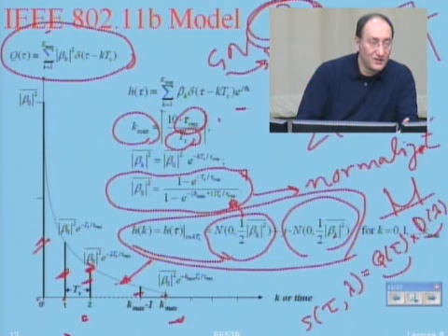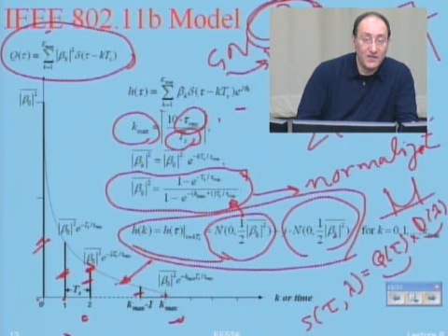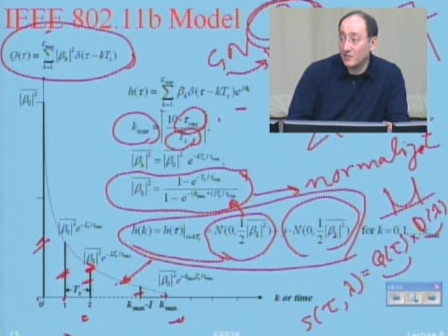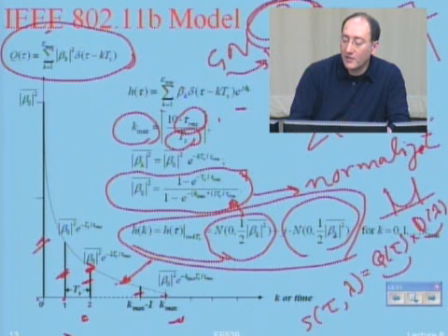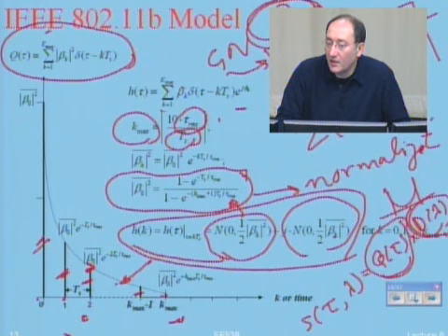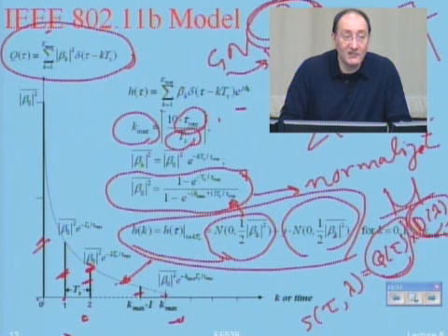Okay? So we had path loss models that we studied in what? In narrowband modeling. So basically, if I want to do modeling, I have a path loss model plus the delay power spectrum, which is this one, plus d sub lambda, which is the Doppler spectrum. Standards, they identify all of them. Now, how come GSM was not doing that? Because in GSM, you are assuming that you have Okumura-Hata's model for the path loss.